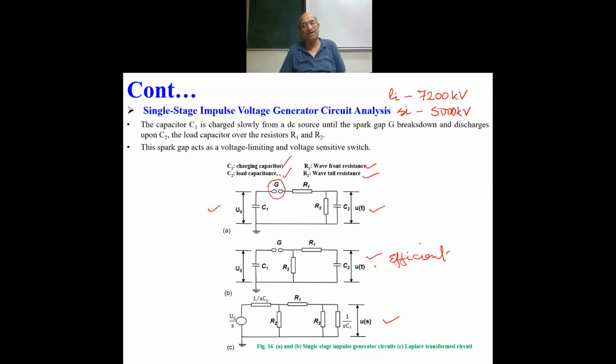The flashover or breakdown voltage would depend upon all these, and you can make a generalized table that for this type of voltage applied, for this size of the sphere, the breakdown would occur at this voltage for this gap distance. The tables are available. Tables were available for decades, even centuries, for more than a century, that arrangement for the measurement went on.